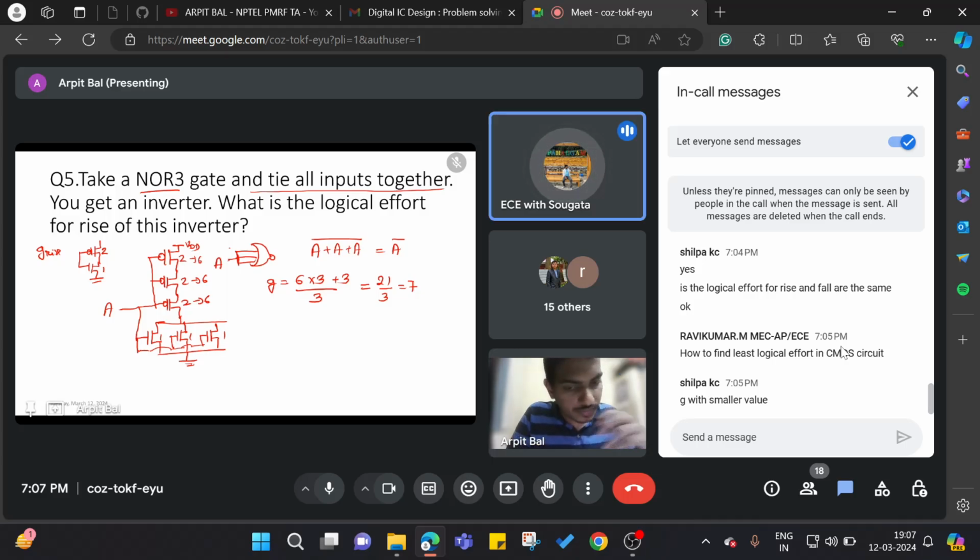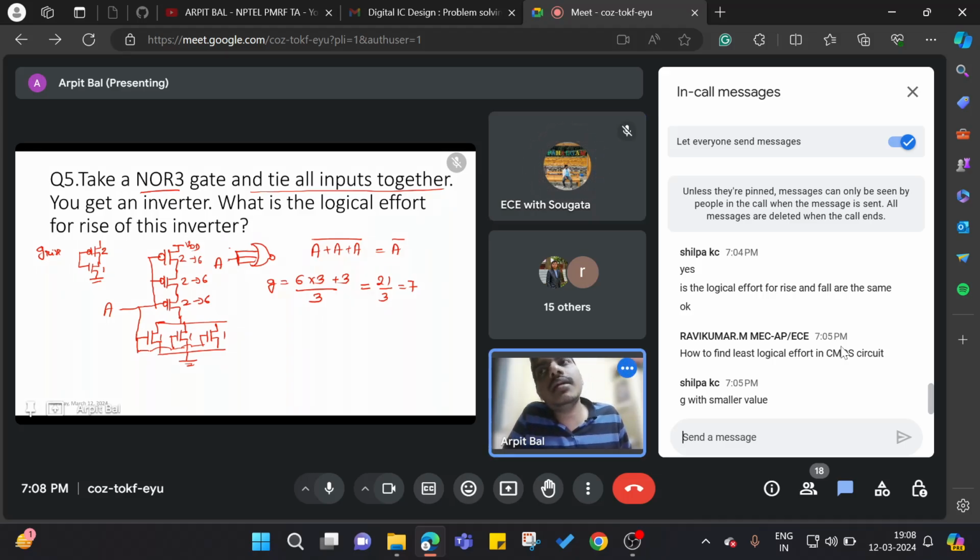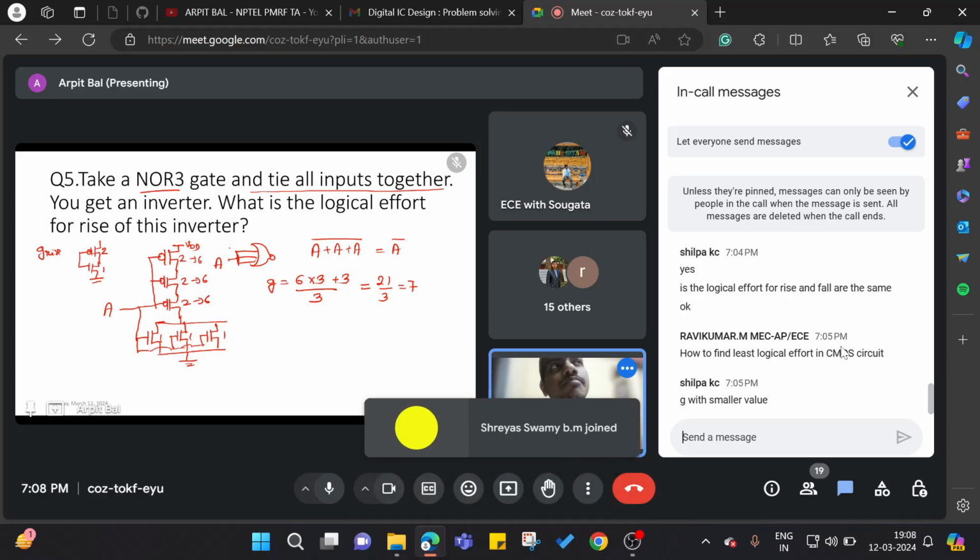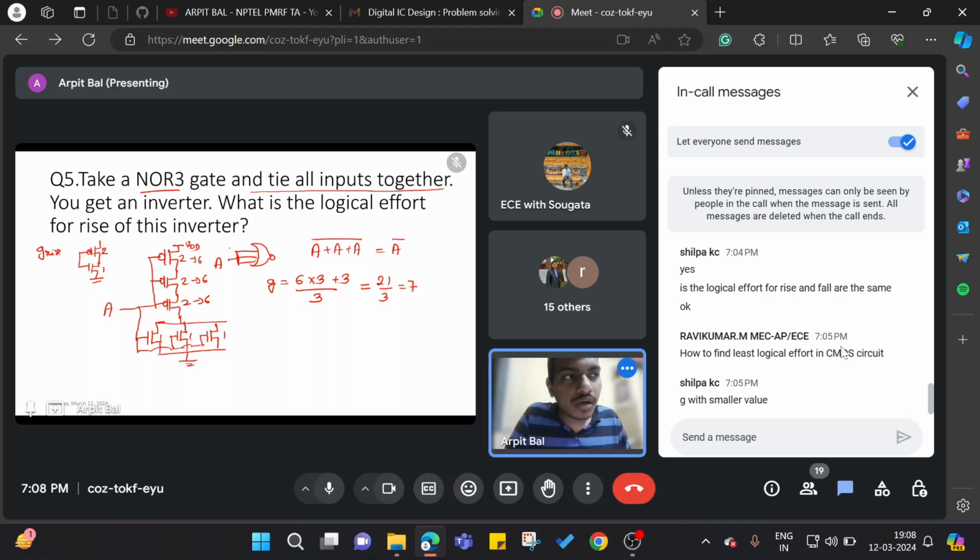Say in earlier weeks, in the live session, there was a question to find the critical path delay using the sizes. One NMOS had 1.5, and I said it was 2. Then you corrected me because it should be the minimum area. Yeah, that is not related to the critical delay. Whatever sizes we were choosing, it should be such that the total sum of all the widths is minimum.